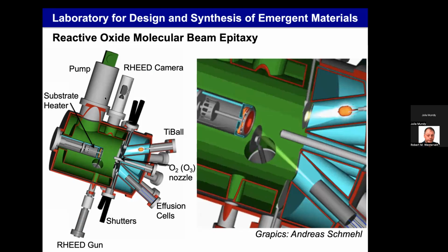Okay. So it really depends on the different elements that you have. Some elements, you'll start to get large amounts of thermal evaporation at maybe 300 C. Other materials, you need to go to 1500, 2000, or even, for refractory metals, much higher temperatures. So it really just depends on the individual element. So this is where, as I mentioned to the people who were here early, this is a quote unquote megabucks evaporator.